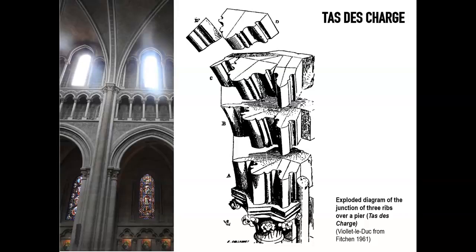Now, the vaults are generally masonry, so stone that could be cut to size. They're not necessarily bricks anymore. Of course, there are examples of bricks used in Gothic architecture too. But they are ribbed vaults defined by pointed arches, and so they imply that there is a position normally in the ceiling space where all these ribs converge and then transfer, as we said, the loads onto a pier internally, and then externally they discharge alongside the buttresses and the flying arches.